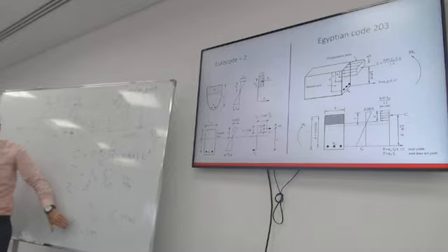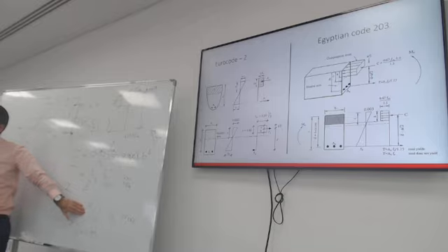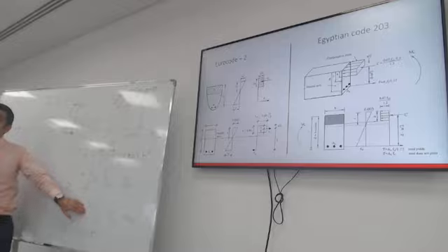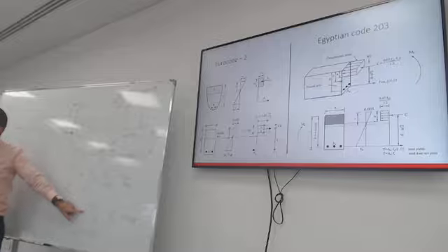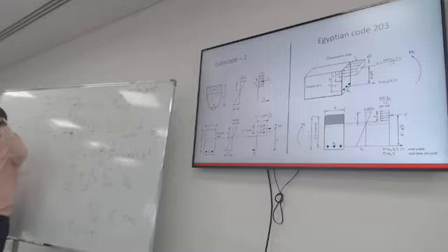What will happen if you exceed the maximum allowable ratio? It's important that you understand this, and that you can answer if anyone asks why it's a critical step in your design, when you're putting in reinforcement, choosing compressive strength, or increasing the depth, why is it so important to limit the ratio between the neutral axis and the depth?